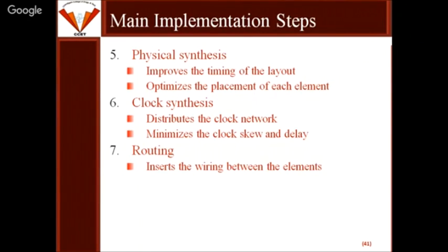So then clock synthesis will be there. It means we have to check that all the synchronous and asynchronous devices are properly connected and functioning properly. And at the last there is routing. It inserts the wiring between the different elements: clock interconnects, power interconnects, and signal interconnects. These are the different interconnections that will be there, and we have to be very careful during the implementation.